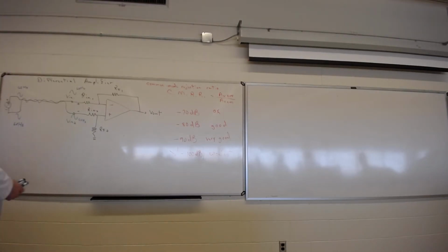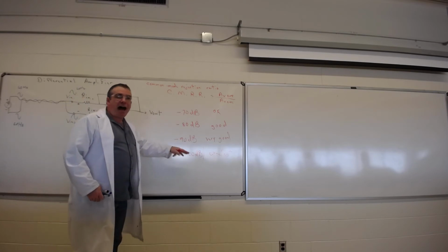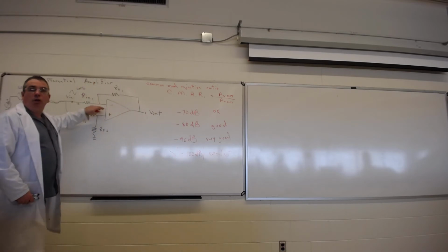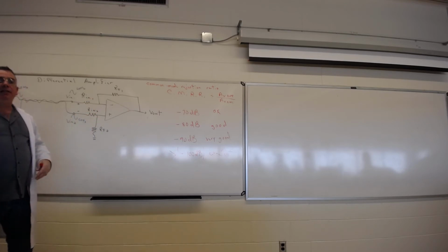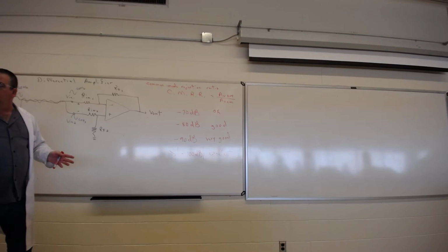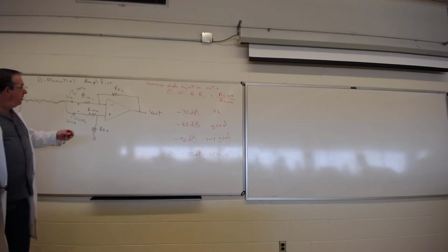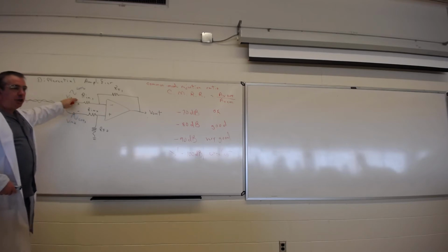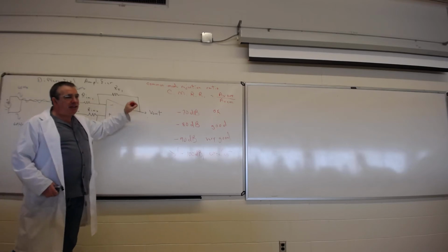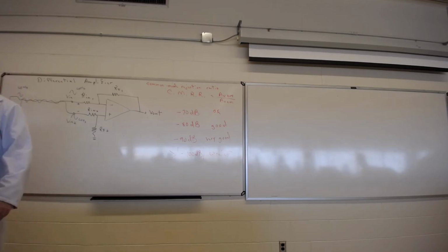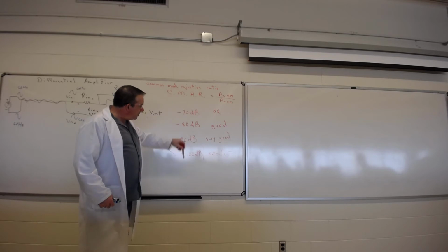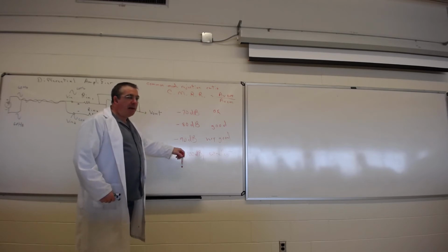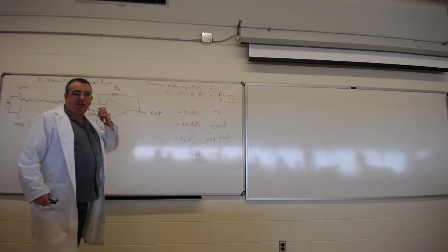And what it is, this number is a measurement of how well an op-amp will reject common signals. The truth is that an ideal op-amp will reject it totally. Okay, ideal. But a real life op-amp, if you had exactly the same amount of 60 hertz on both sides, a tiny, tiny wee bit is going to leak through, but very little. And the smaller this number, okay, the better it is at rejecting common noise.